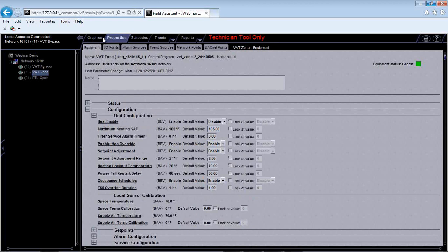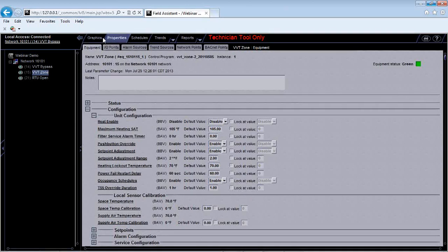All right. Now we have a maximum heating supplier temperature. This is referenced for if you have reheat, but with a zone system, the heating supplier temperature, you really don't want it to go above 95 degrees. Ideally, you want 90-degree discharge air coming out of one of these guys. That is per ASHRAE's recommendation. However, that's not always something that is possible with a rooftop unit.